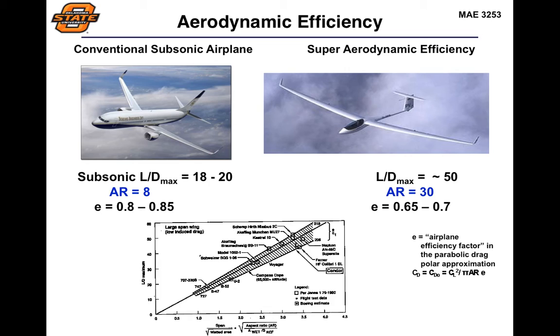So when we take our 2D airflow profiles and turn that into an actual wing with a finite span, we find that there's a direct correlation between the maximum lift-to-drag ratio that we have and our overall wingspan or aspect ratio of the aircraft. And again, if we want to try to make that improvement, we can go back to these basic physics. And this is an excellent plot to start to look at, which compares basic geometry characteristics of your aircraft with the maximum lift-to-drag ratio that is possible from that.